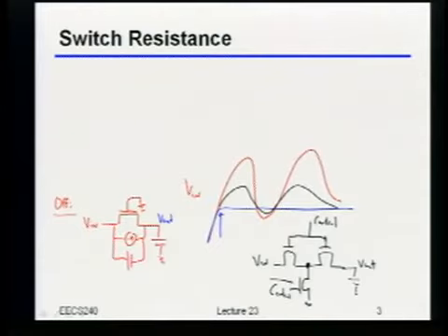So as an example, what I've drawn here now is, let's say I'm sampling the output on a capacitor, and, I'll draw it a little bit better, the capacitor is referenced to ground, right? If I want to make sure that none of this makes it through to touch my output, let me just ground the other side of the switch, right? Because if this is grounded and this is a nice low impedance, then even if I have capacitive coupling over there, there should be nearly zero chance for that to make it all the way through to the other side of the switch.